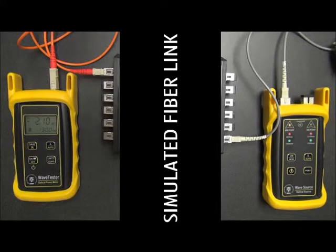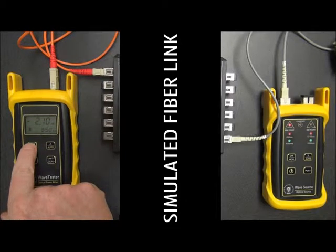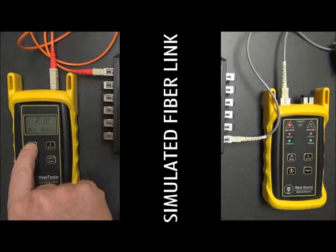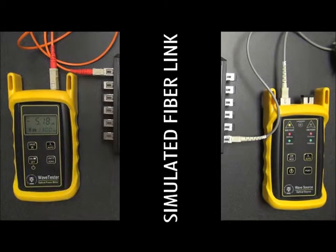And the nice thing about the WaveTester, again, is because we're in auto mode, we can hit the save button one time, and it stores an 850 and a 1300 reading for port number 1. Now, when I hit the save button, you'll see what happens here. Because it's storing 2 readings, the test reading number 2 will show up here. The reason being is because we stored an 850 reading and a 1300 reading together.